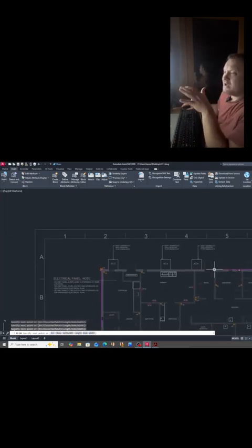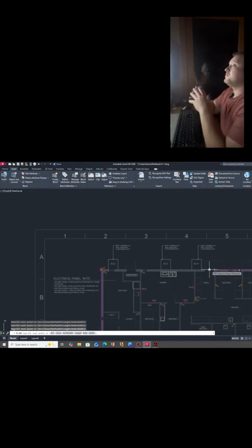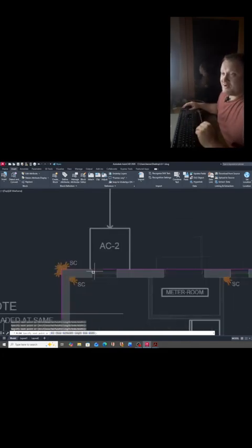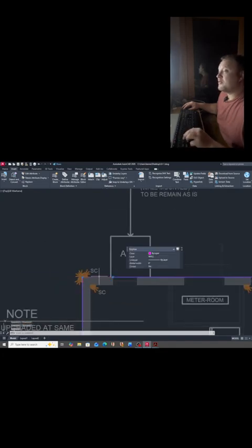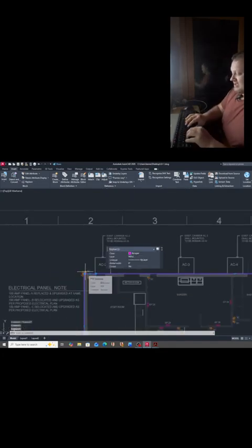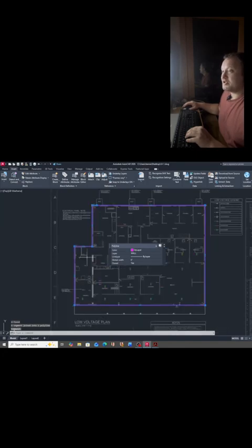And AutoCAD, I will say, it also will allow you to bring in a PDF and convert it into CAD, but I will say it can be messy. I don't want all this information on, and I want to be able to control what I'm doing. So I like bringing in a PDF, and any draftsman or CAD guy can go through and kind of clean this up really fast and draw the walls, and it doesn't take that long. So I'm going to type in join just to make sure everything's connected, and as we can see, I have the outer building shape.